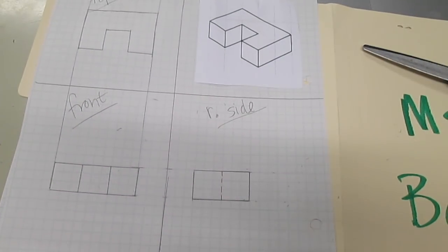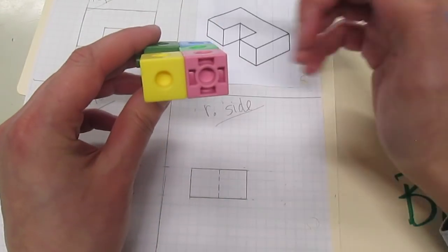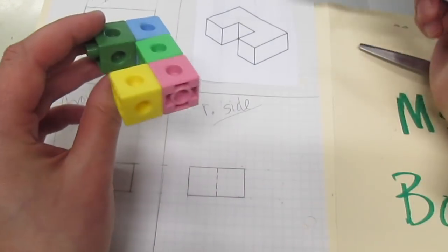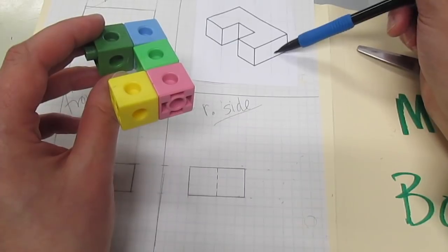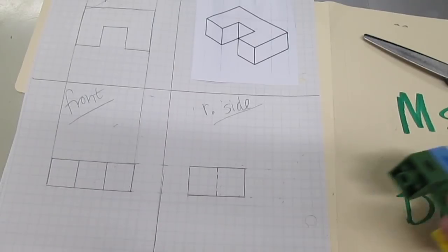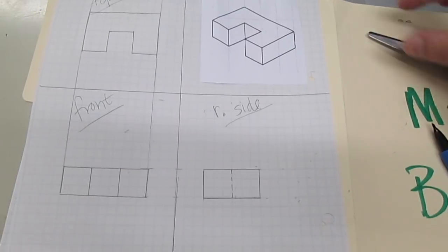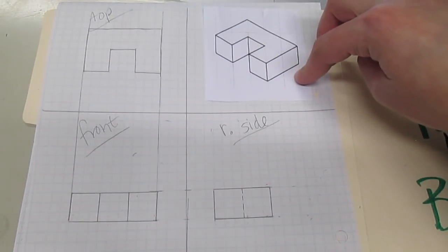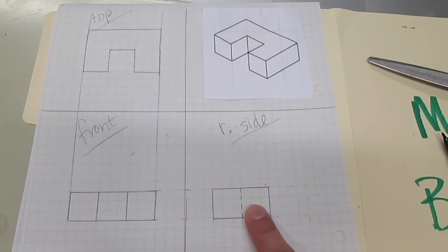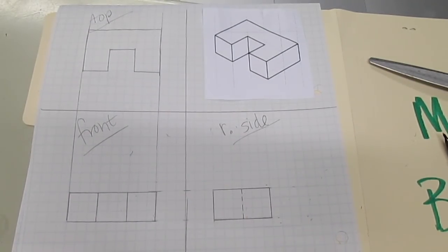And that is because from the right view, there's a hidden edge here. So from the right view, there's this hidden edge. So we use a dotted line there. Okay, so this is what a completed multi-view sketch would look like with the isometric. The top view lines up with the front view lines up with the right side view. And you are set to go on